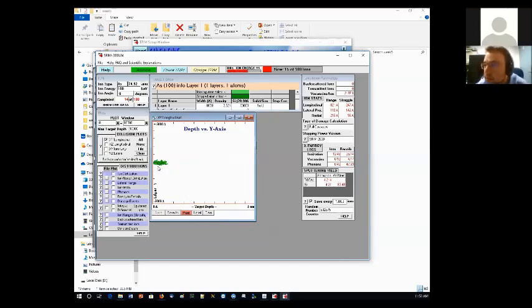But I want you to see one thing. It's not just showing us the arsenic, but it's showing us the damage that it's creating inside the crystal too. These green ones are now the interstitials. They're the knocked off silicon atoms from the crystal. Okay, so wherever the arsenic is going, of course, it's taking a little longer.